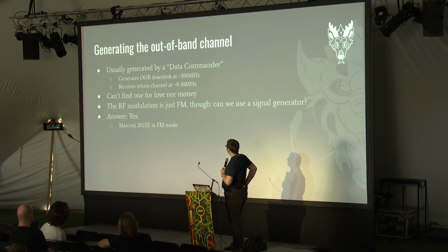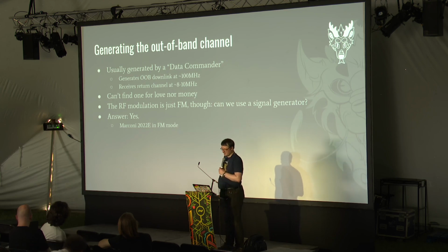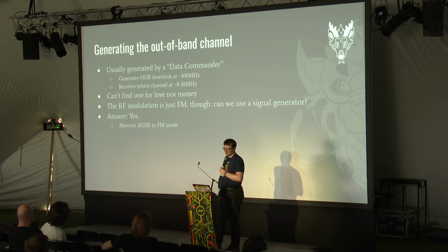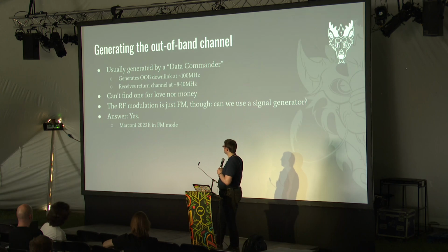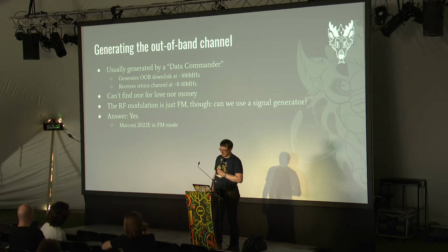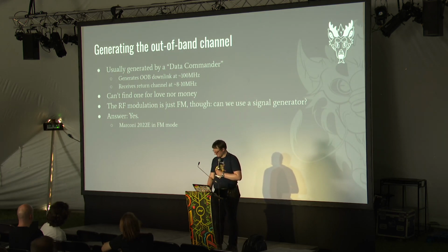But the signal that comes out of that needs to go into a box called a data commander, or would normally go into that on the head end. That generates a FM modulated, or FSK modulated if you prefer, version of the incoming data, and that's what the cable boxes listen for. But you can't find them, or I haven't been able to find one in 2.5 years. But it's just FM modulated. It can't be that hard.